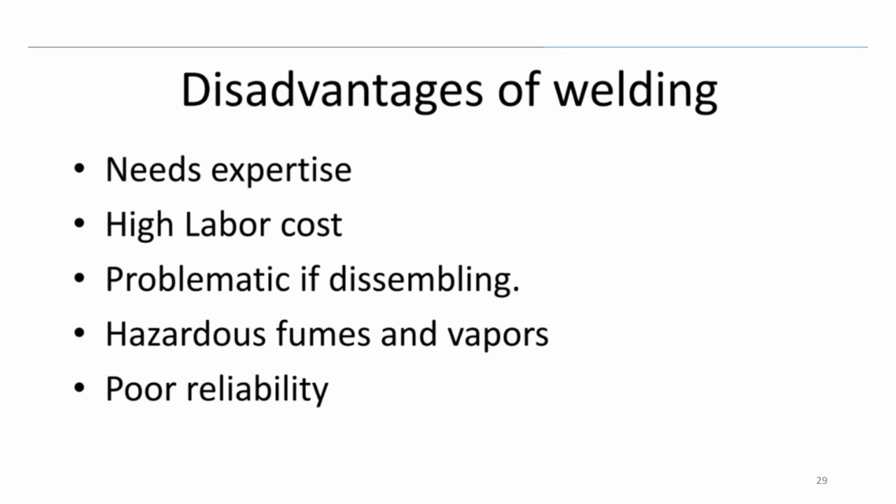At the welded parts, near the weld there will always be some residual stresses and some distortion, and that always leads to crack initiation when some type of loading is applied. So it is not always as reliable as a part that is not welded at all.